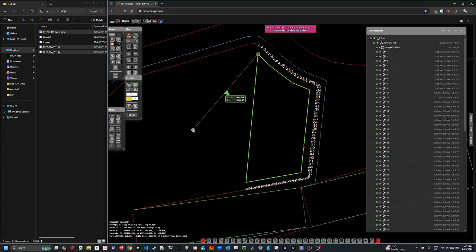But I kind of don't like where that is, because I think I want to get my distribution at my wall correct. So I'm going to hit the escape key, and that will stop the tool. We'll go back to that tool and select this, and go along this way. In the same way, the shallower numbers, the smaller numbers in the blast holes, are going to be on the left-hand side. Okay, click there, and then I'm going to use a reference point.